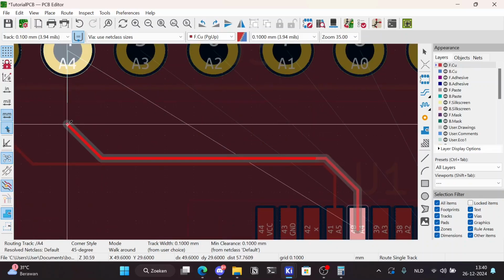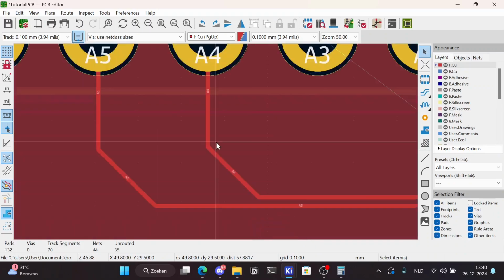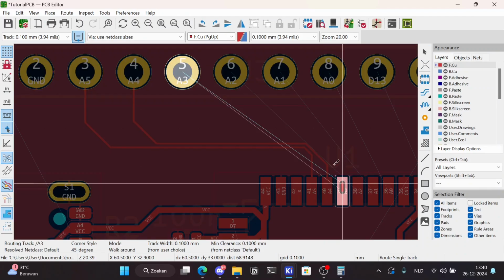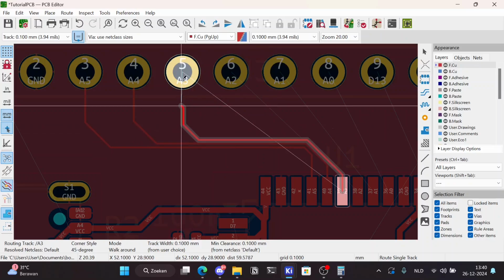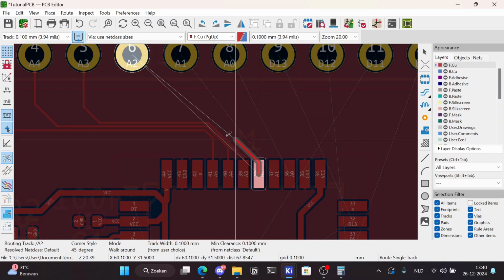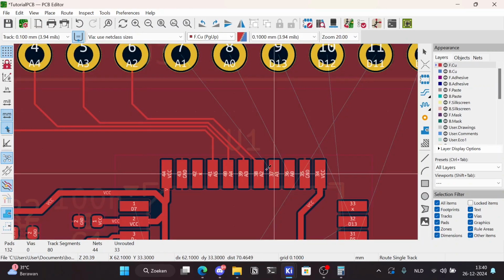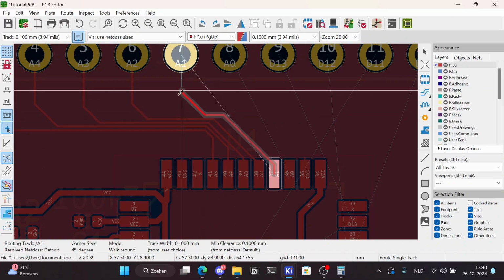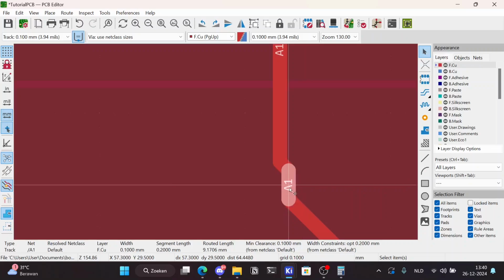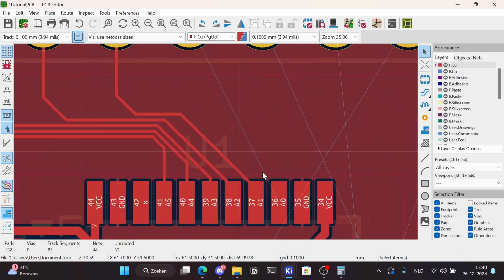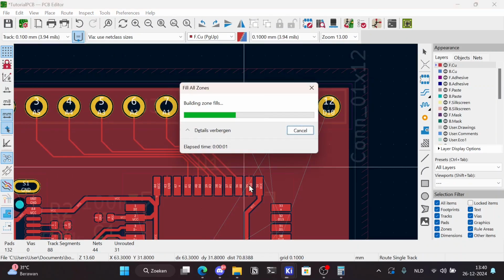and then you see this wiggly trace. It's kind of annoying, but you can fix it. Yeah, and route A3. Again, that squiggly part. No, never mind. And then A2, A1. As you can see, that squiggly part's back again. Jeez. And then you can end it with A0. And press B if you're finished.